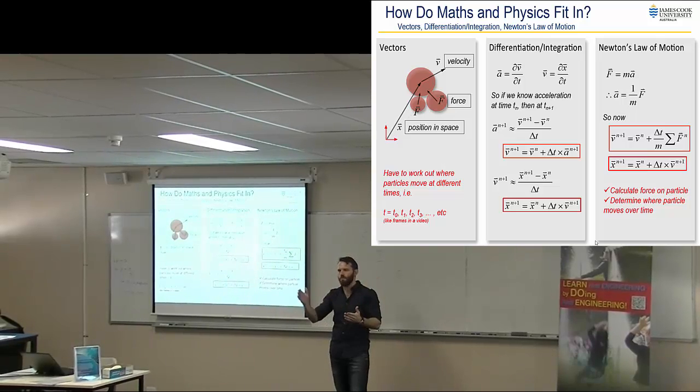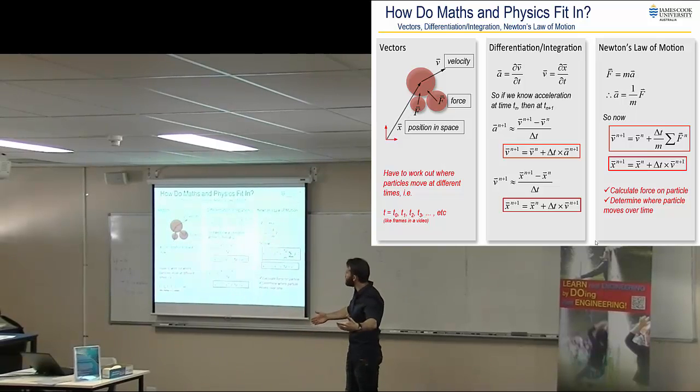And so you just track where your particles are and do a search between particles at every time step, and any that are overlapping, you put a force between them, and that actually then repels them from one another. You just need small enough time steps that you don't get particles overlapping by a lot, because then you get a very large force. So you want very small overlap, and you control that with the time step, but otherwise it's fairly straightforward to calculate.